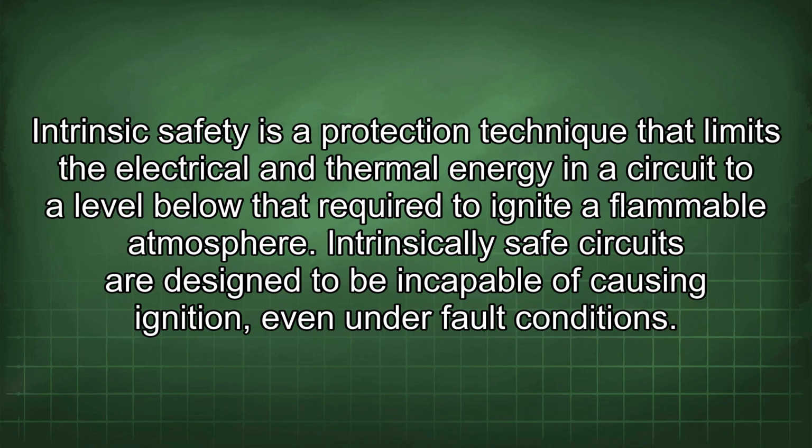Intrinsic safety is a protection technique that limits the electrical and thermal energy in the circuit to a level below that required to ignite a flammable atmosphere. Intrinsically safe circuits are designed to be incapable of causing ignition, even under fault conditions.